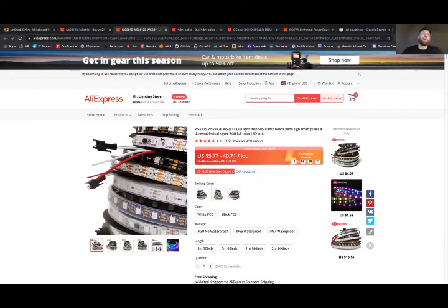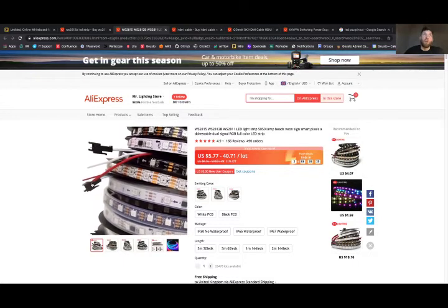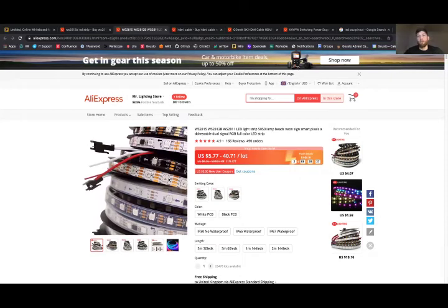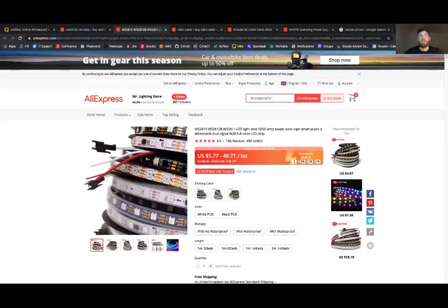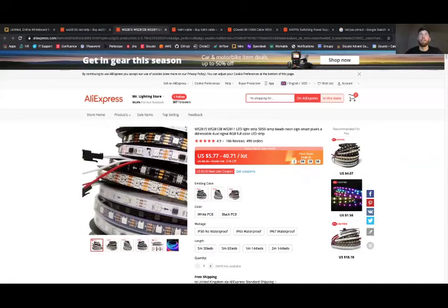Okay, and you need to know exactly what each of those wires does, and you need to have a method of connecting them into your circuit appropriately. The JST connectors standardize this, so they make it into a simple male-female plug and socket scenario, which makes it very easy to chain these things together and plug them together without doing any soldering.